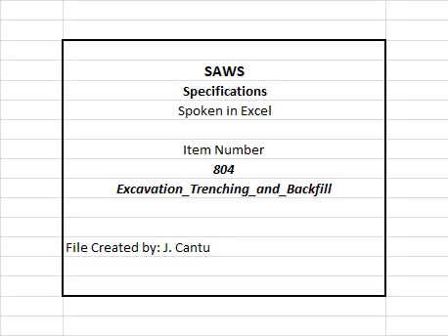3. Trenching. A. Trench walls shall be vertical. B. Open trenches are limited to 200 feet open at one time. C. Contractor shall compact trench and install an all-weather surface on any paved surface, roadway, or trench as directed by SAWS inspector, prior to proceeding to the next section. Sections are limited to 200 feet of open trench. D. Projects under 500 feet must be completely restored at the end of each day.